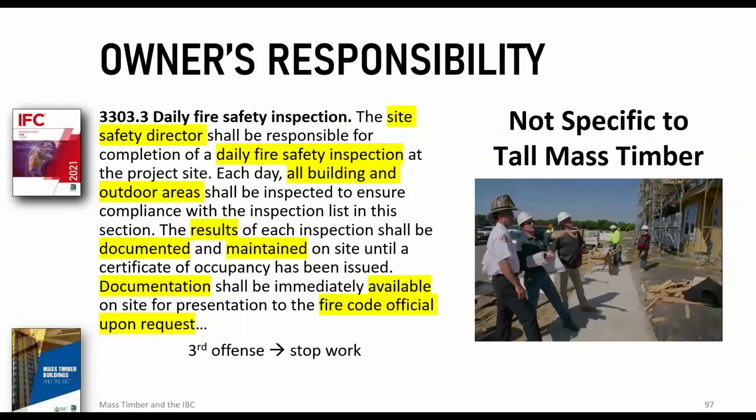Okay, now this is not specific to mass timber. This is the daily fire safety inspection. This is not something that the jurisdiction of the AHJ does. This is an internal inspection where the site safety director, that's a new term in the 2021 edition of the IFC, it used to be called the Fire Prevention Program Manager, but they changed the language to site safety director, shall conduct or make sure it's conducted, daily fire safety self-inspections on the exterior and the interior of the construction site and the subject building.